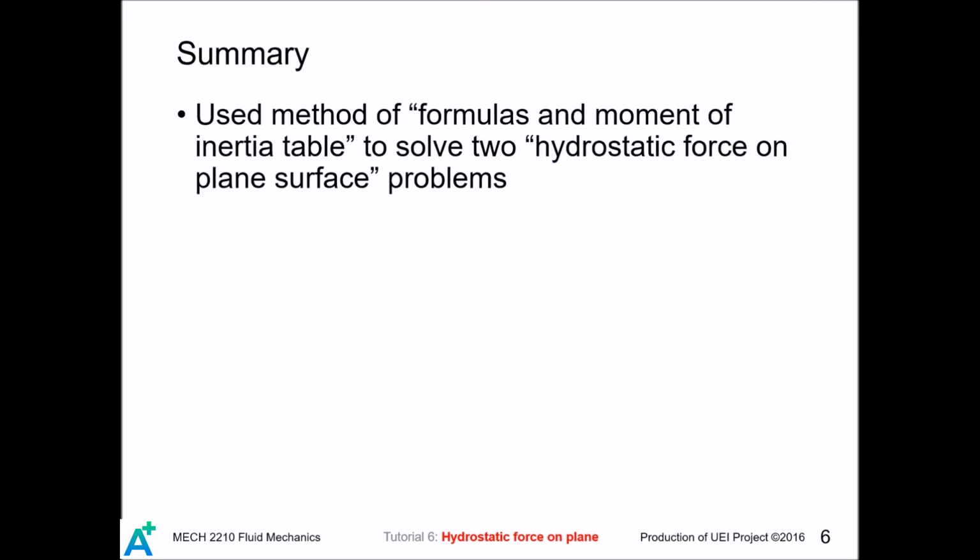So today we talked about how to use the formula and inertia table to find the hydrostatic force on a plane surface, how to find the pressure center, and how to use that to find the moment. We also went through 2 examples to illustrate these skills. Actually, the concept of pressure prism is just a special case when we consider the section area to be rectangular. I will only make an extra video about that if I have time.